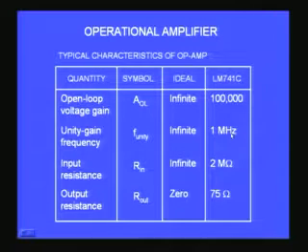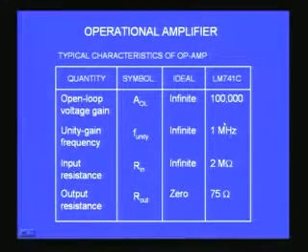So as long as you have a gain of 1, up to 1 megahertz the gain will be almost the same. It will not fall from 1, it will perhaps come down to about 0.7 times or 70% of 1, but the bandwidth is 1 megahertz, which is a very large number, 10 to the power 6.